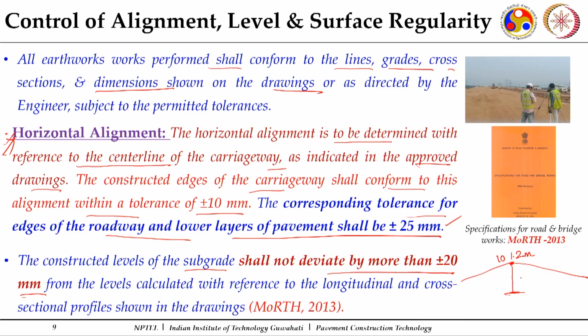Now, when it comes down here, I can say I have a crest of around, say, 1 meter. So, this will come up to be 100.2 meter. So, this will be my subgrade top, and when it will come up a subgrade of a thickness of half a meter, this will come up in that case 99.7. So, this will be just at the bottom of my center line. The level of the subgrade bottom will be 99.7 if I am doing a construction for half a meter of subgrade.